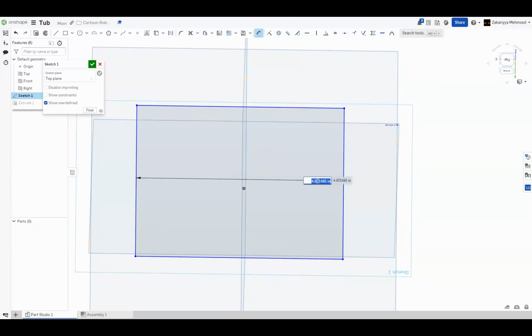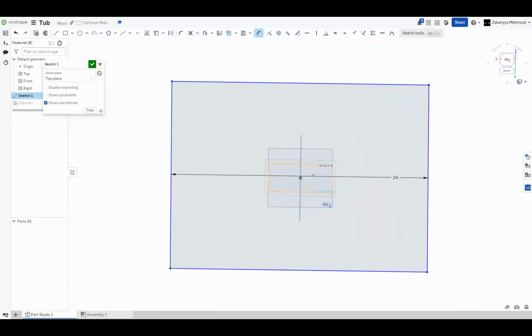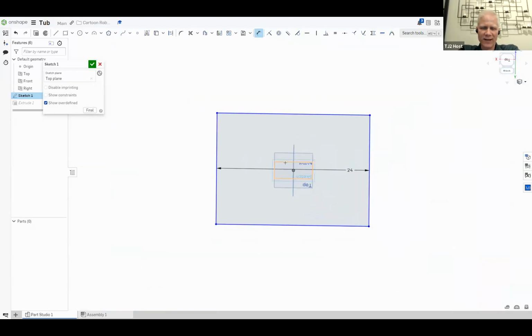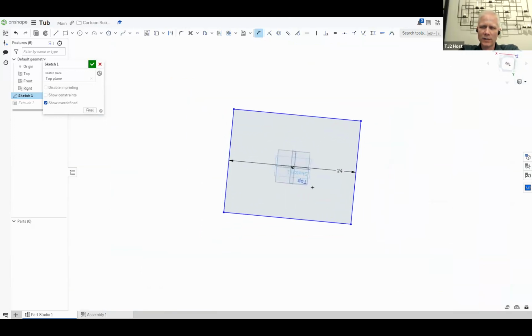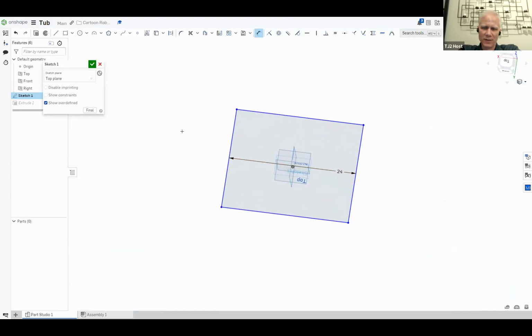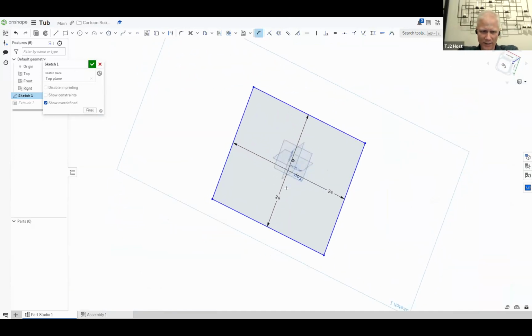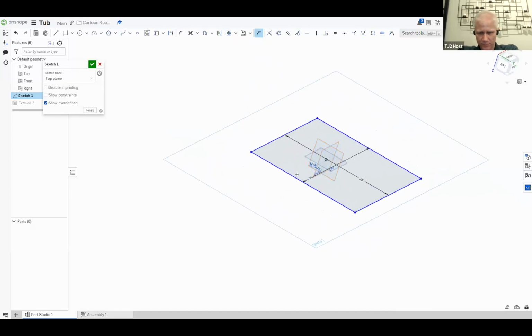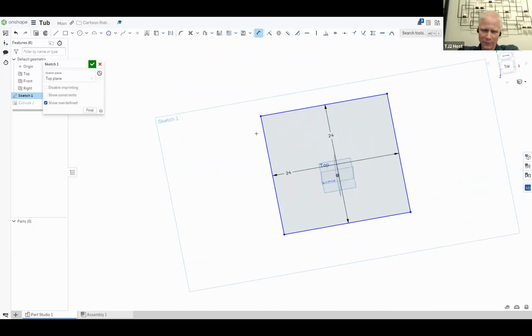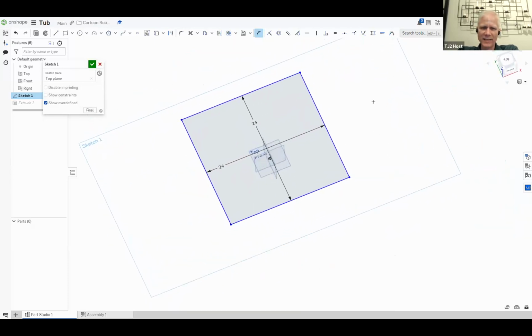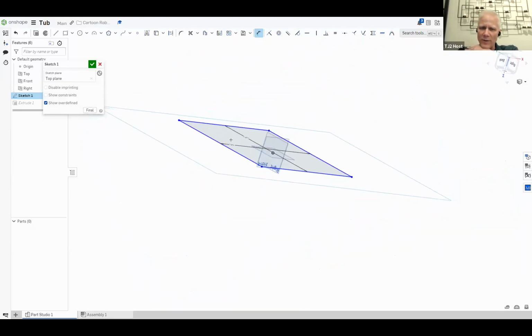24 inches, yep. And I don't know how much room silver is going to have, but let's assume it's an 8-inch ball. So let's assume that we're going to need something like 6 inches or so for silver's intake. So if it's a 25-inch wide robot, and we want to be right up to the back, but we need 6 inches off, so we need to be 19. So I make it 19 on that dimension. One of the dimensions should be 19.